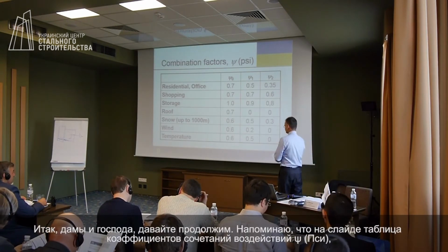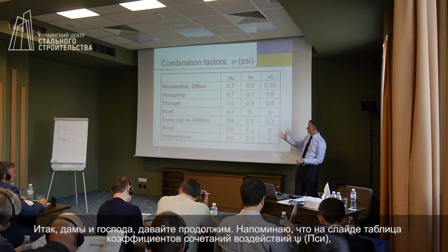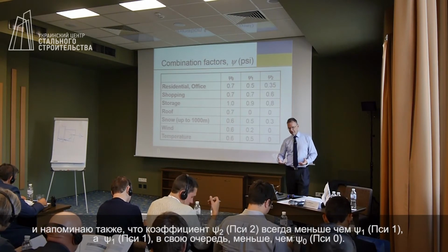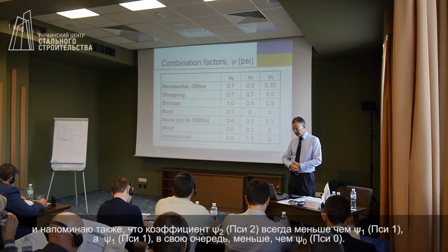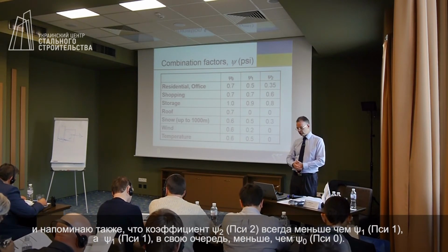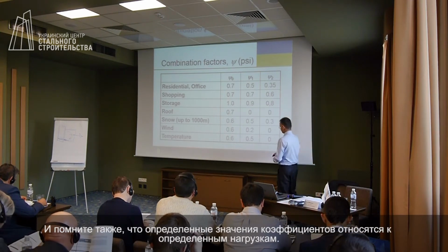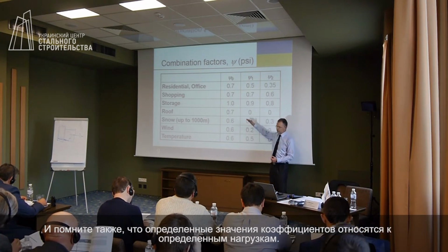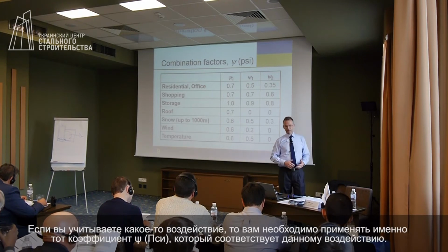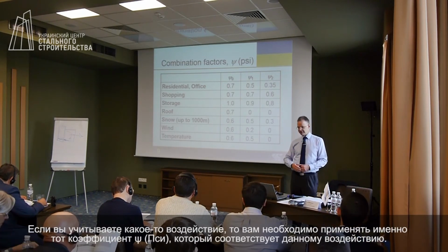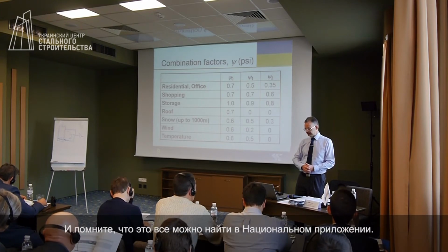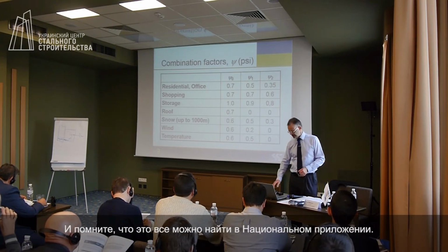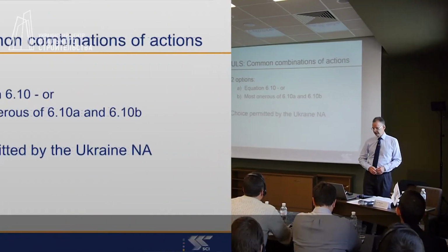So ladies and gentlemen, we'll continue now. These are the psi factors. Remember that they vary. Psi 2 is smaller than psi 1. Psi 1 is smaller than psi 0. And remember that a particular value belongs to the type of load. If you're considering that type of load, then you need the psi factor for that type of load. And remember that you find these in the National Annex.